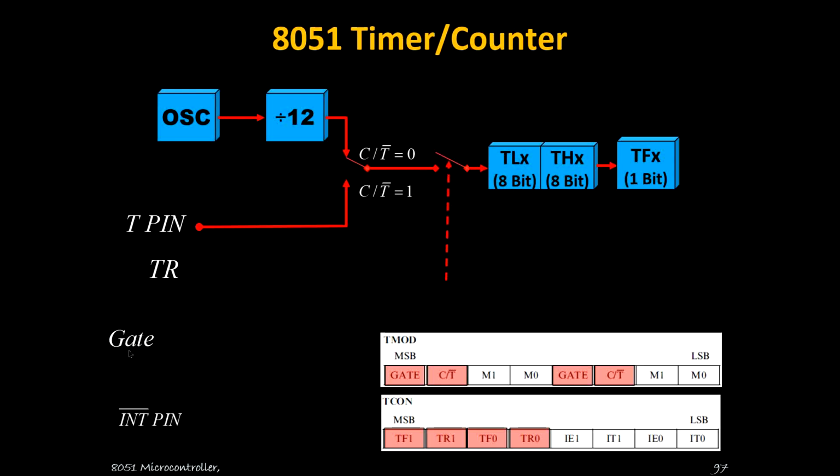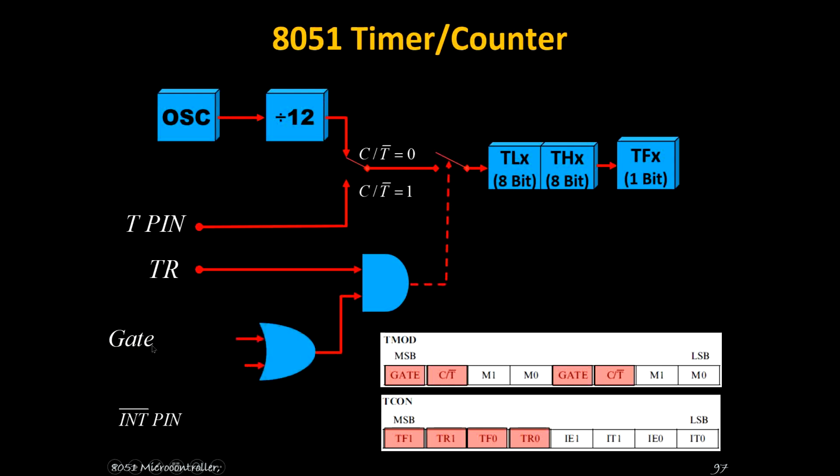Whenever we need to start or stop the timer, we are using the interrupt. So in hardware we can stop or start the pin. Once the timer has started with respect to your gate input, the gate being 0 or 1 decides start or stop of your timer register.